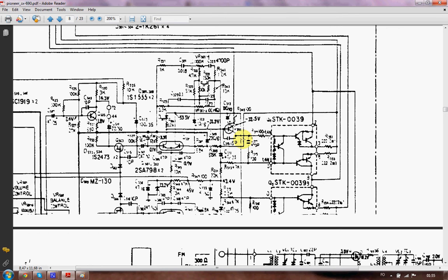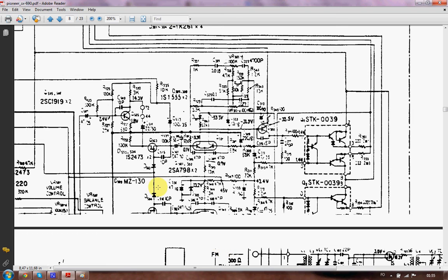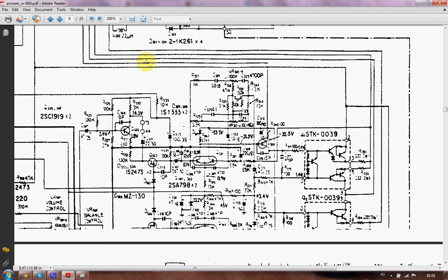So if you get a good reading on your oscilloscope on the suspected input, which is around right here from these transistors, and if you look further up right here, we should see constant voltages. I mean, to this terminal 2 here, which provides the main amplifier with power, where we should see a constant good number of direct voltage. You can trace this wire further back, and I know that this is going to be constant direct current, which you should expect on here.